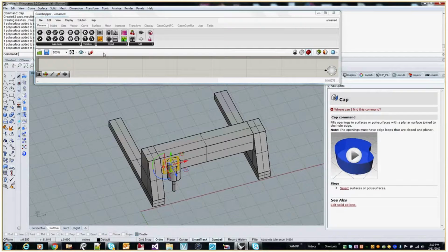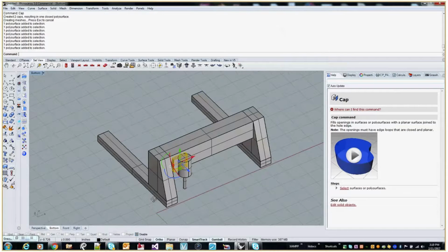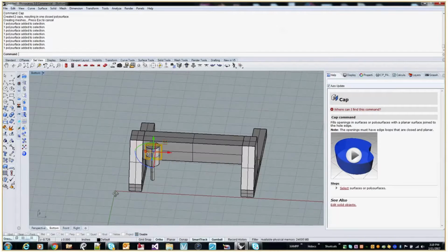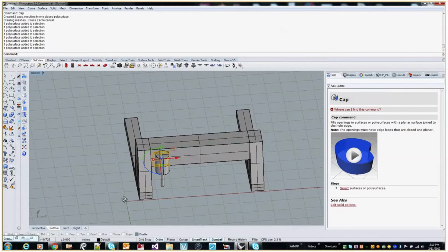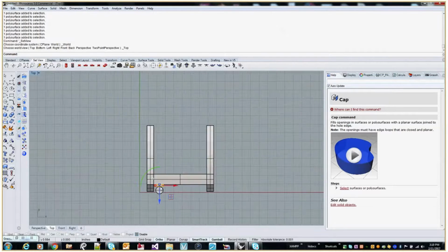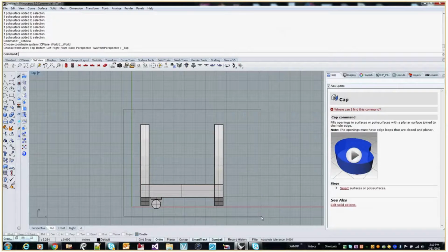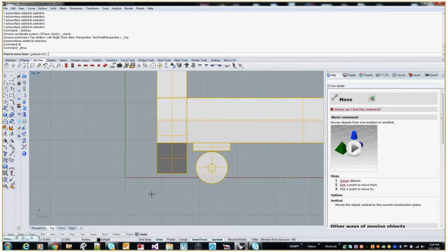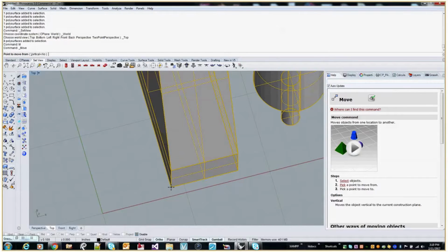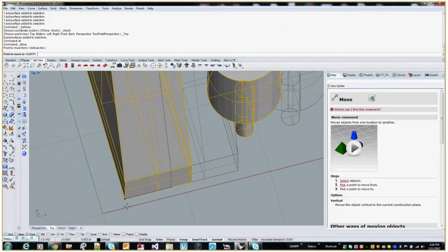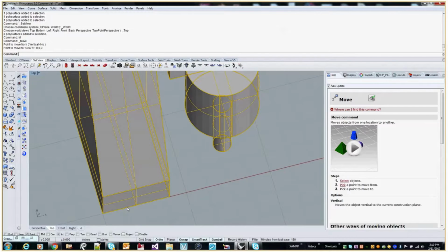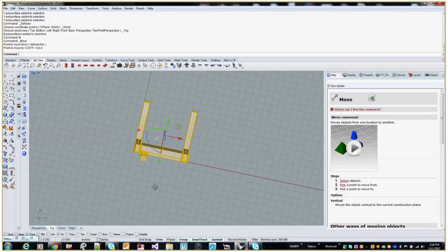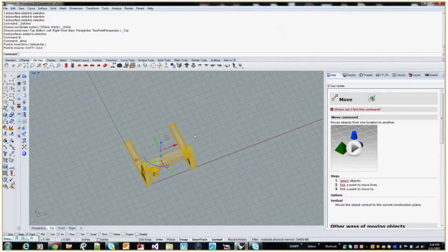Before we get too far into this, it's easiest to work from a 0,0 origin. This isn't lined up to that, and I want to make sure that we do that before we start to make the definitions. That just makes things a lot easier. So I'm going to move this from its lowest left point. Go ahead and turn on our object snaps here. Grab that, just type in 0, 0, 0, get it to the origin, and now everything should flow real smooth from there. So, got the parts.